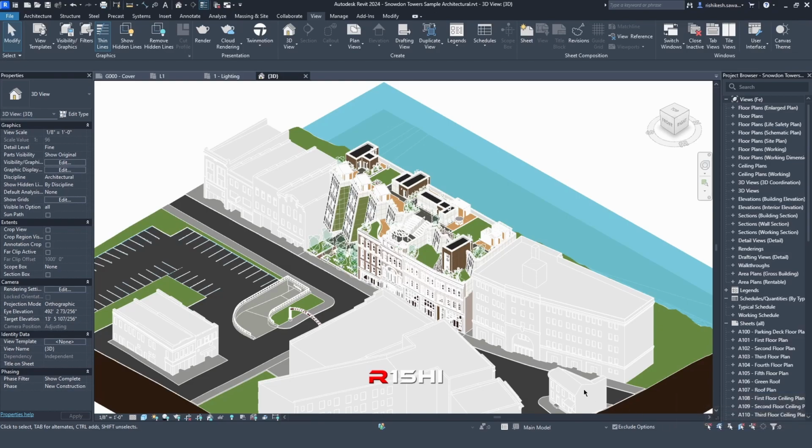Okay, same way, if you have pinned or fixed some objects onto your model and you don't want to accidentally select and unpin them, then you can say don't select the pinned objects. So this is how you can decide which filter will help you in which situation. It is a toggling option. You will eventually be toggling different filters according to the work you have to do on the project.